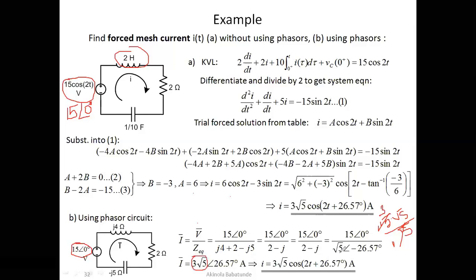All right. Again, for phase angles, we are going to subtract the phase angle of the denominator from the phase angle of the numerator, and that gives you 0 minus what we have at the denominator. Since we already have another minus here, it becomes 0 minus minus 26.57. That becomes plus at the end of the day, and that's why we have just 26.57 right up here.